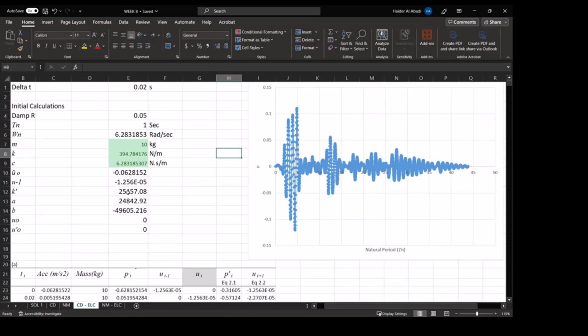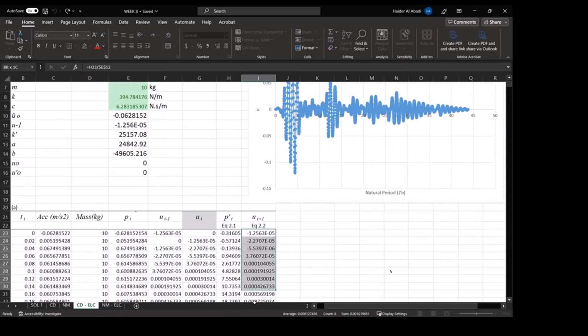for making the spectrum. Now, you're going to see later on that once we have one condition, and what I mean by condition is a specific time period and a specific damping value, here the damping was 5% and the time period was 1, we will be recording the maximum response. Where is the maximum response here? It is this point. Yes, it's this point here. Now, how do we calculate this point? By finding just a simple function, say maximum or minimum of this figure here.